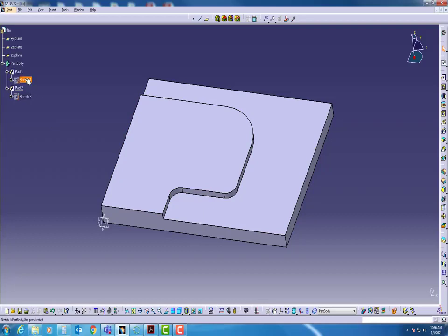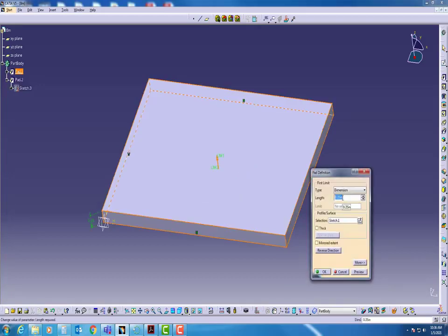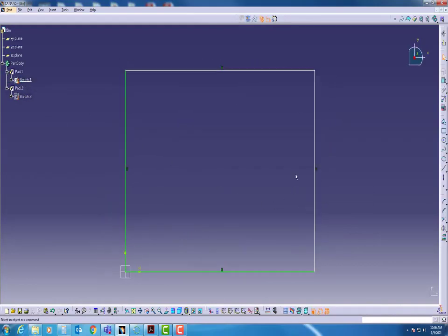So let's go back to Sketch. I don't want to change the pad. The pad is the thickness. Okay. If I double click on it, the thickness is fine. We got that right. What I want to do is I want to change the sketch. Well, if you'll remember, we just made a rectangle. We didn't do any constraining. So I'm going to double click on my constrain, and I'll just make this 4 inches